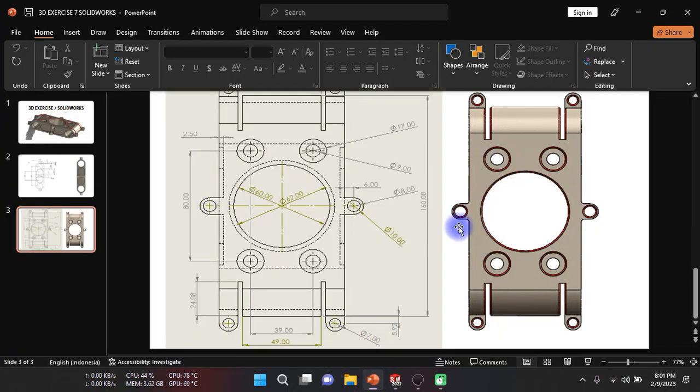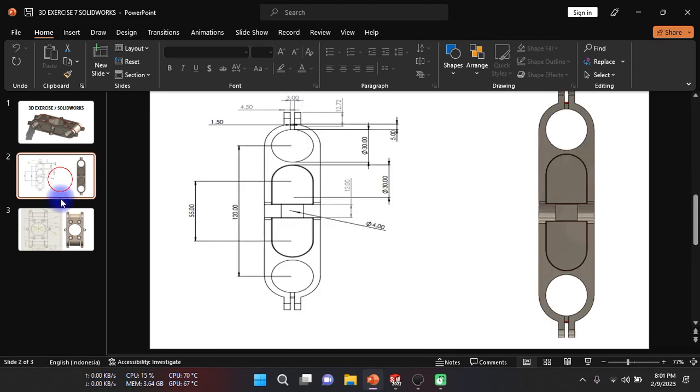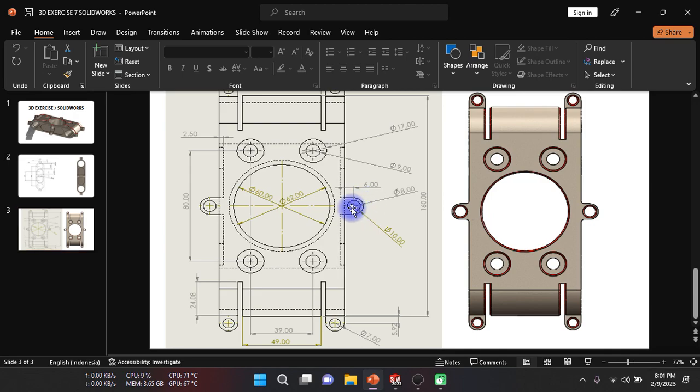Okay, after that we can create this horn too here, and if you see the finishing sketch in the exercise, you can see here like this the visualization of the sections. And if you see the sketch, we have two separate holes here. The first hole has a dimension of 10 mm, and this center hole is 8 mm, and the distance from the center point of this hole to this line is 6 mm.